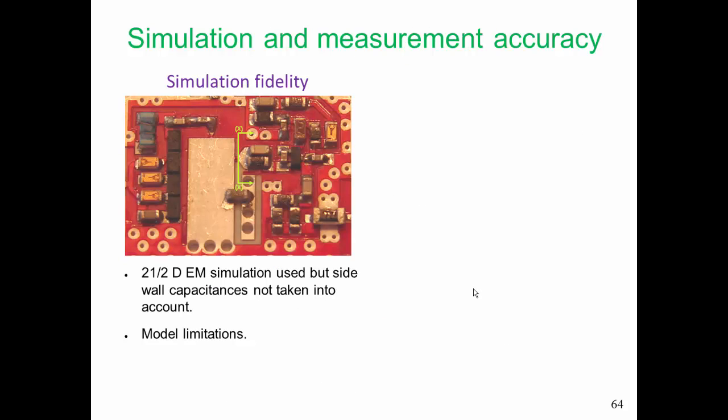So let's summarize the difference between the simulation fidelity and the measurement fidelity. Now, our simulations used EM simulation of the passive components and the layout. It used 2.5D EM simulation. 3D simulation of a structure like this would be very difficult.